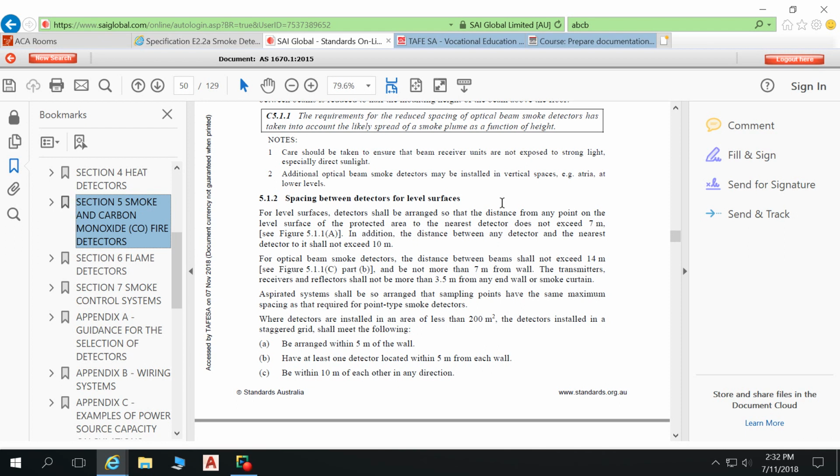So in terms of fire safety, the NCC is a little bit sort of choose your own adventure. You can incorporate a sprinkler system, which means that you don't have to incorporate some other systems, or vice versa. And it makes far more sense with this building not to incorporate the sprinkler system. So that was set out in the video for Monday.